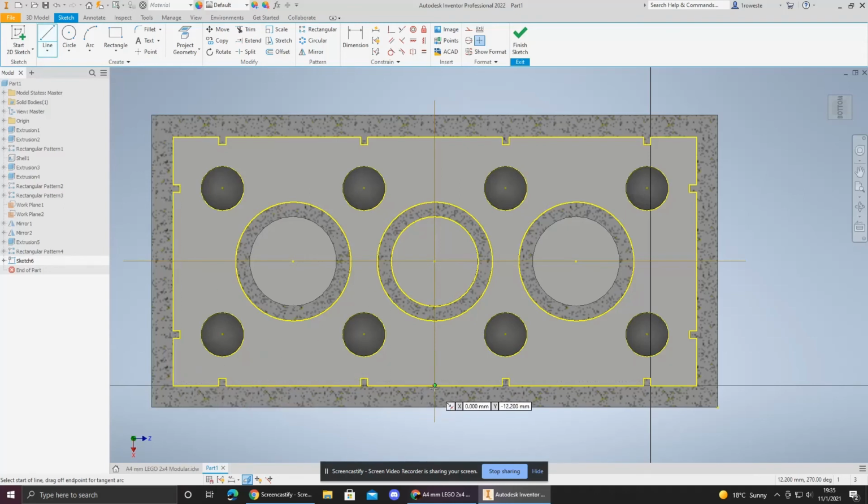Of course, this lighting up green indicates that it is the appropriate midpoint, from here until here, all the way up to the other midpoint. And to confirm, we can see that it is 180 degrees. This black line indicates that it has been fully constrained through a midpoint to a midpoint. This cannot go anywhere.